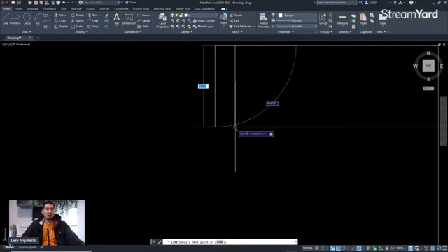So once I do that, I'm going to do it again. Hover over this and then move your mouse to the side and you will see an X. That white X is called extension, and you're seeing it over there on this blue square. This is another precision setting that is activated and it's called extension. It's very useful to draw more efficiently in AutoCAD.